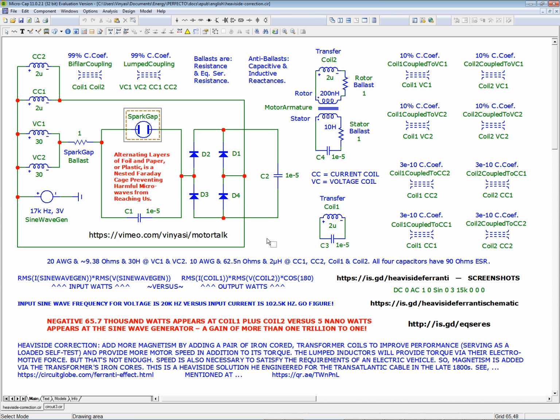But if I go the opposite extreme, I'll get matrix is singular problems. Now, putting in a resistor here was what I initially did. Now, I keep all my resistors as a legacy of what their purpose was supposed to be, even though I've reduced them all to 1 ohm, because I think they act as a locator for the equivalent series resistance of other components, such as the coils nearby and all of the capacitors, to find a location to manifest their hidden potential.